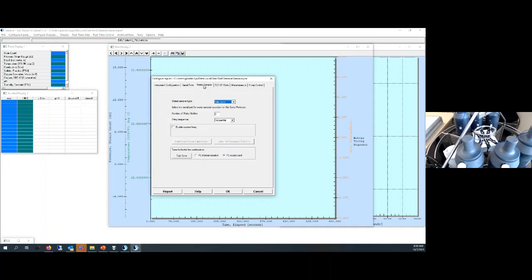Now I'm going to click on this water sampler tab. And if you haven't used a deck unit before, by default, this might be set to none. Once you're using the SBE 55 or say a SBE 32 or a different kind of water sampler, not from Seabird, you'll need to specify that here. So I'm going to click on SBE Eco. That's the SBE 55 Eco water sampler.